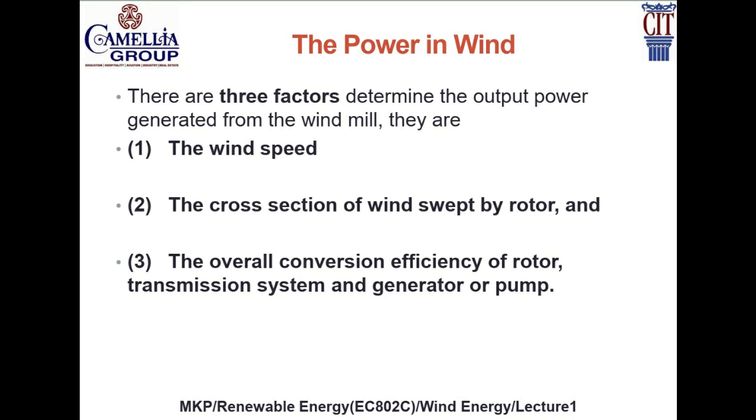No device, however well designed, can extract all the wind's energy, because the wind would have to be brought to a halt, and this would prevent the passage of more air through the rotor. The most that is possible is for the rotor to decelerate the whole horizontal column of intercepted air to about 1/3 of its free velocity.